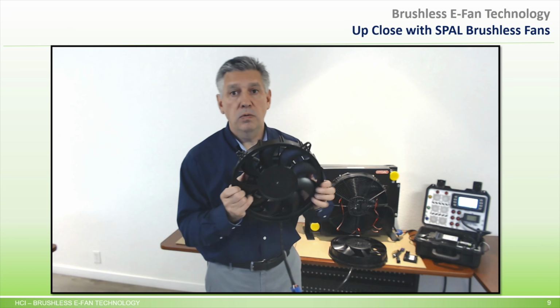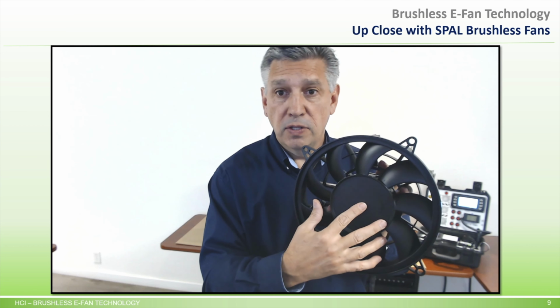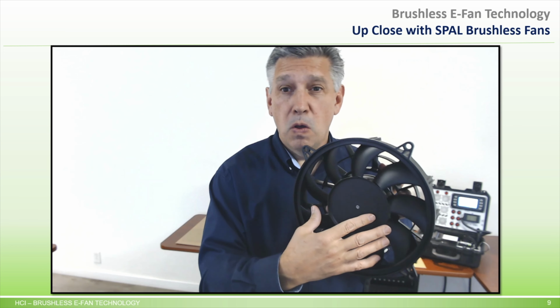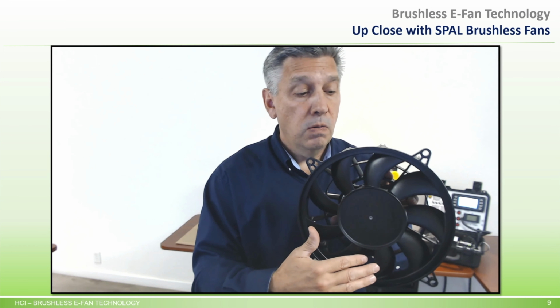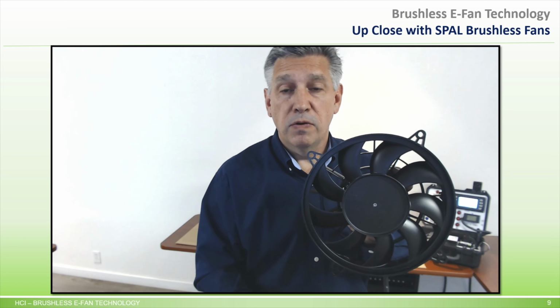Also, one thing to note, and we talked about this earlier, is the slinger blade. Very important for harsh environments. I've used a lot of brush fans through the years. A lot of them hit something small and bend one of these fan blades, and it's done. So attaching it all together with the slinger blade, very important for harsh environments.